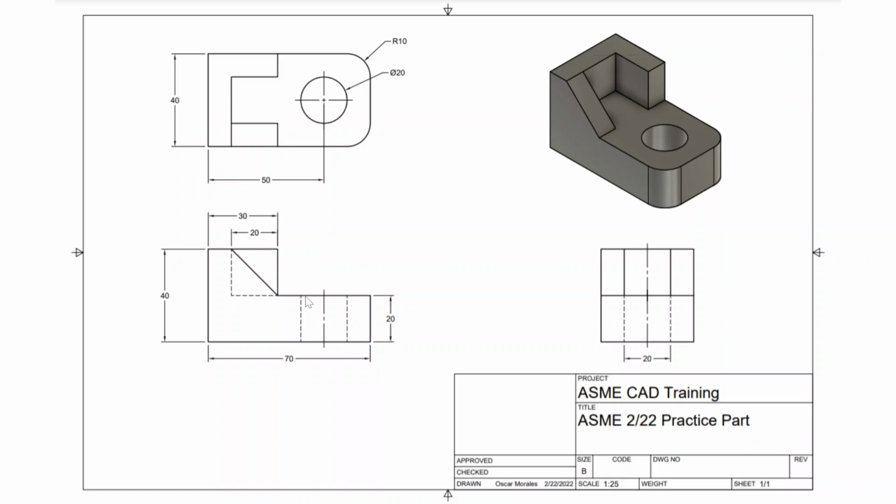All these other dashed lines are hidden features, but those are the 3 types of lines, also the solid lines. So those are the 4 types of lines that you really need to learn for reading drawings. Again, you have your solid ones, which is what you can see. These little lighter dashed ones are what you can't see. These are center lines, which mark the center of a hole from a side view, and these are center marks, which mark the center of a hole from a top view, where you actually can see the diameter and the radius and all that.